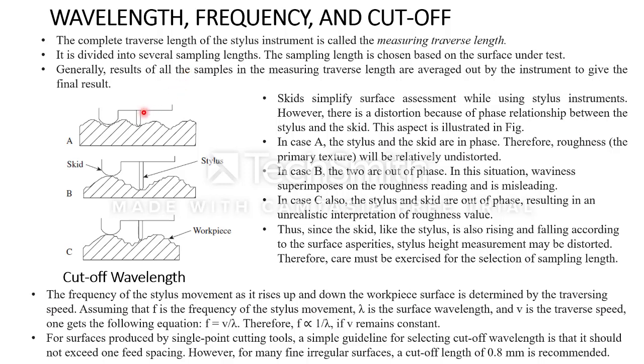And one more thing is, generally the skid is used to give support to the stylus, right? So the skid simplifies surface assessments while using stylus instruments. There will be some distortion between the skid and the stylus. Because of the distortion, there will be a phase difference between the stylus and the skid.